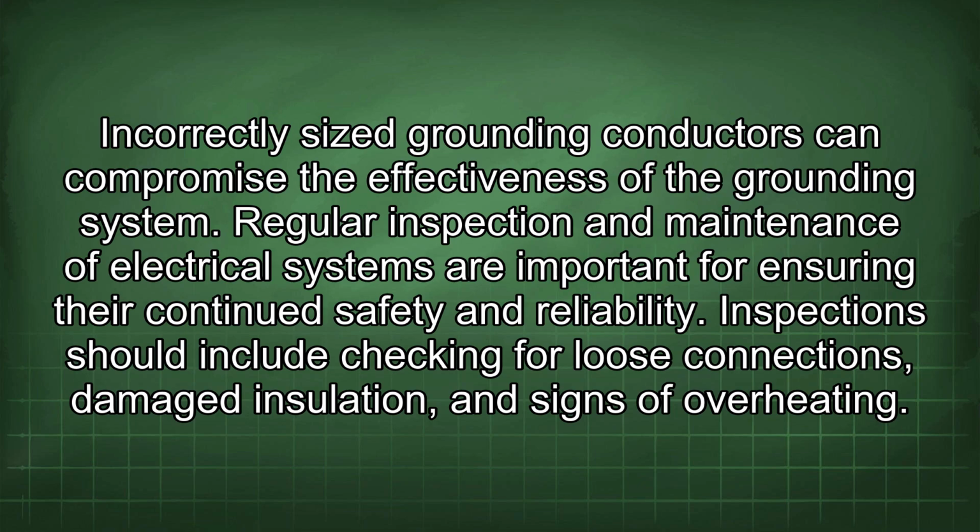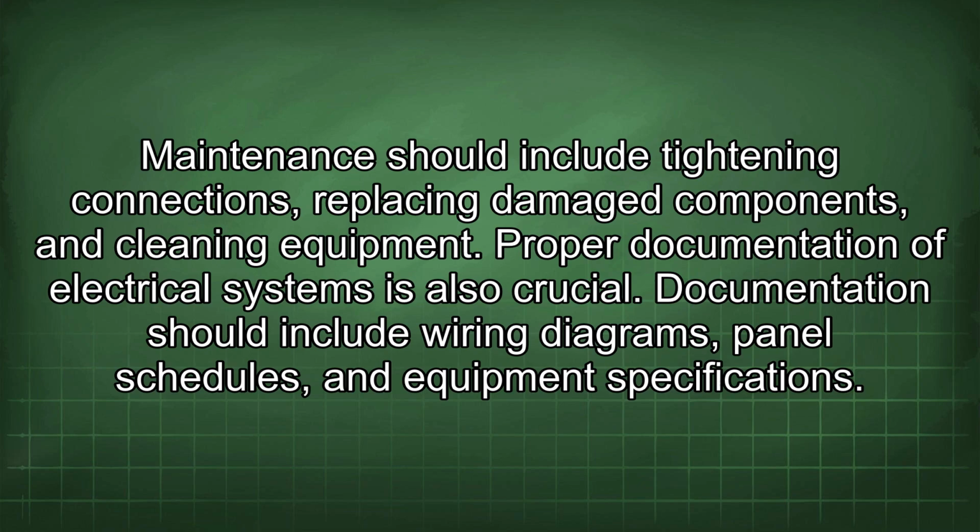Regular inspection and maintenance of electrical systems are important for ensuring the continued safety and reliability. Inspection should include checking for loose connections, damaged insulation, and signs of overheating. Maintenance should include tightening connections, replacing damaged components, and cleaning equipment.